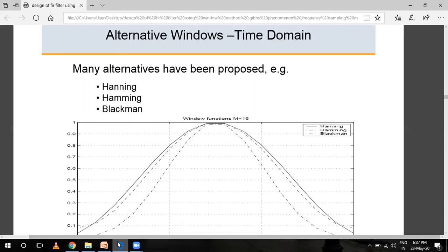When we discuss the difference between the Hanning window and the Hamming window, both windows are similar, but the Hanning window touches zero at both ends, removing any discontinuity, while the Hamming window stops just shy of zero, which means the signal will still have a slight discontinuity. See the difference: Hamming and Hanning, double M and double N.